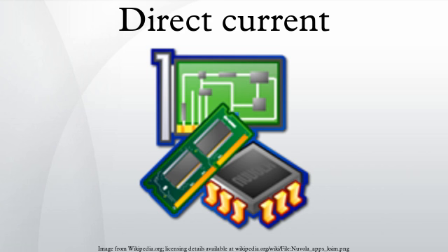The DC component is defined to be the expected value, or the average value of the voltage or current over all time. Although DC stands for direct current, DC often refers to constant polarity. Under this definition, DC voltages can vary in time, as seen in the raw output of a rectifier or the fluctuating voice signal on a telephone line. Some forms of DC have almost no variations in voltage, but may still have variations in output power and current.